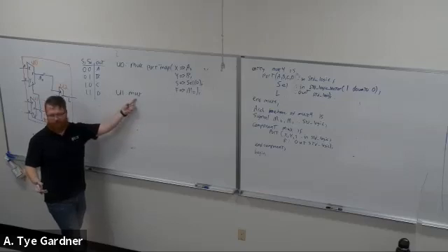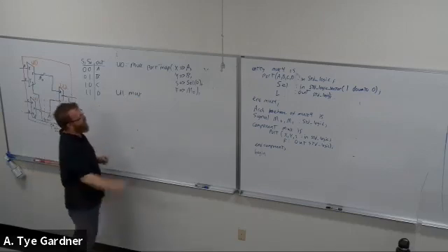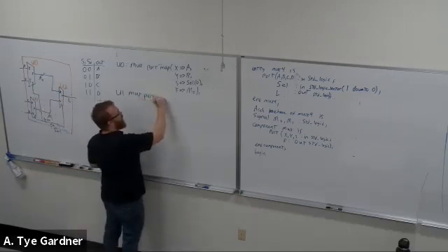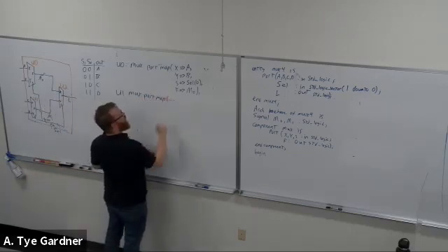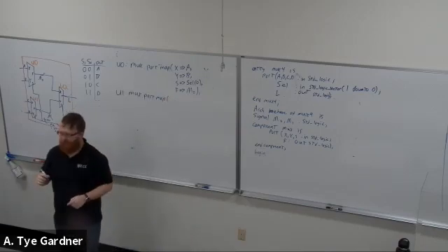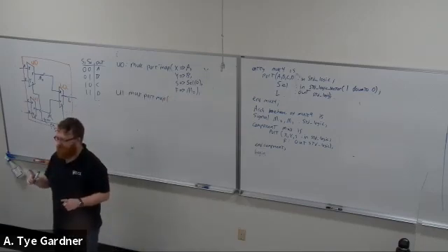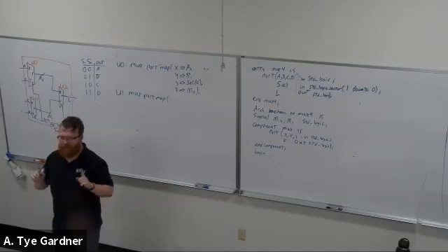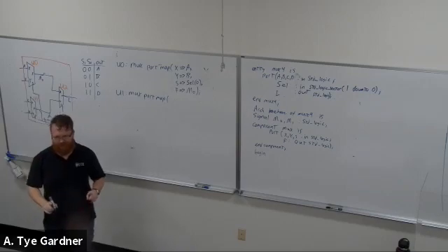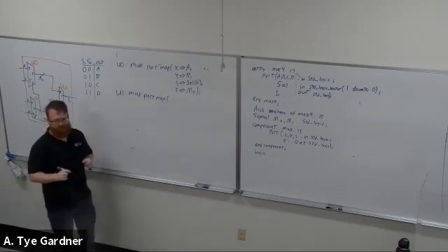I'm reusing code. We call that code reuse. Super fancy, right? It too has its own port map. And this is the other way of writing port maps. This is the worst way of writing port maps. You will do it, but you shouldn't. The reason you will do it is because it is shorter.